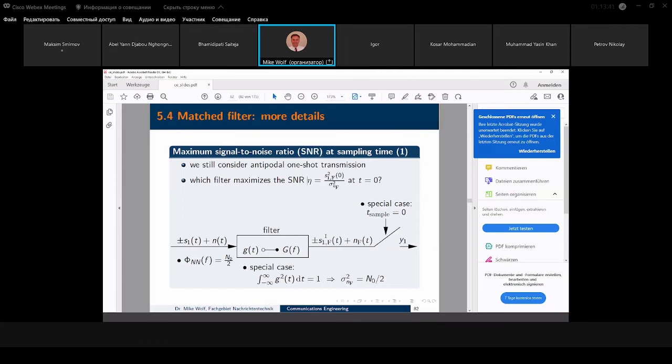And then I need to develop a filter which is matched to the sinc functions, and I cannot make this filter impulse response causal because the sinc function is infinite in both directions. So there is no causal filter, no real-world match, it's just a limit which we can obtain for transmission. Let's see. So I assume the only difference compared to this g of t is just c1 of minus t.